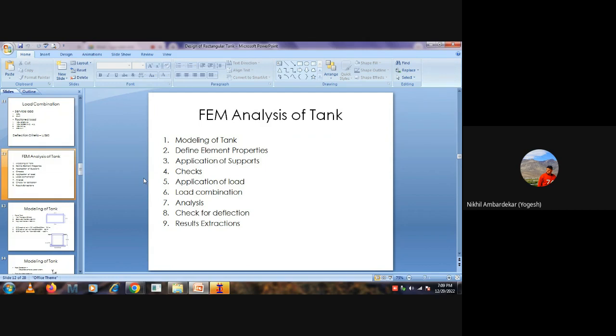After that we have to apply the different loads in our STAAD model. Before that we have to calculate them manually, just as we did for the PCA tables. In any method, it is obvious that you have to be ready with all your loadings that need to be applied in STAAD, or used in your hand calculations.